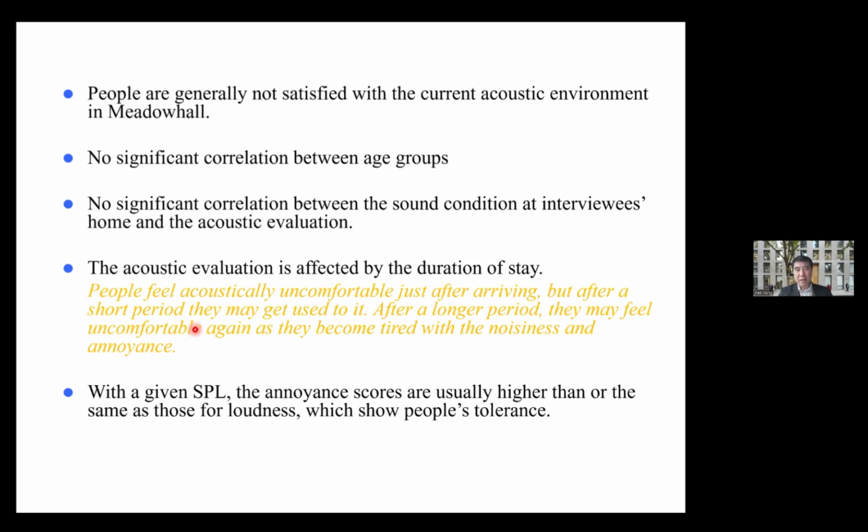So what does it mean for design? It means, of course, we need to reduce noise level and reduce reverberation time, to make people feel comfortable when they first arrive. But more importantly, we should have a place for people to rest after a certain period. We found that at about half an hour, 40 minutes, people become uncomfortable again. So for about every half an hour, 40 minutes of shopping distance, not walking distance, we should design a place for people to rest and quiet zones so people can recharge, become comfortable again, and continue shopping. So this is the power of considering people's perception to guide design.